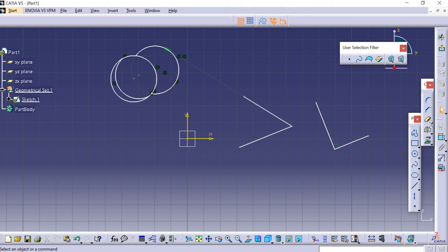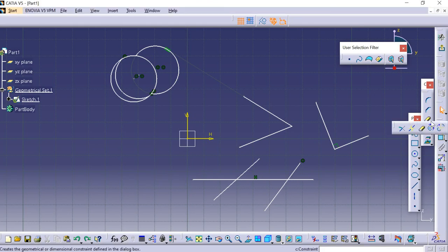So we also have other options on break. So imagine we have a line and two other lines intersecting it, and we use break. We select this line, then the line outside will get trimmed, but the interior line will remain the same. Now the same way, if we use this, the line which we have selected will get trimmed. Now this will show the number of intersections here. It will show 2, 3 horizontal intersections.